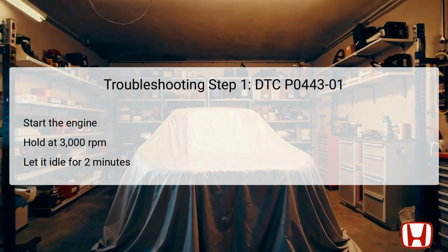It's crucial to maintain this engine speed until the radiator fan activates and subsequently allow the engine to idle for about 2 minutes. This procedure is designed to help the PCM gather relevant data, facilitating a comprehensive inspection of the EVAP system's components. If the check engine light remains illuminated after this procedure, you will need to continue following the subsequent inspection steps for a more in-depth diagnosis of the issue.